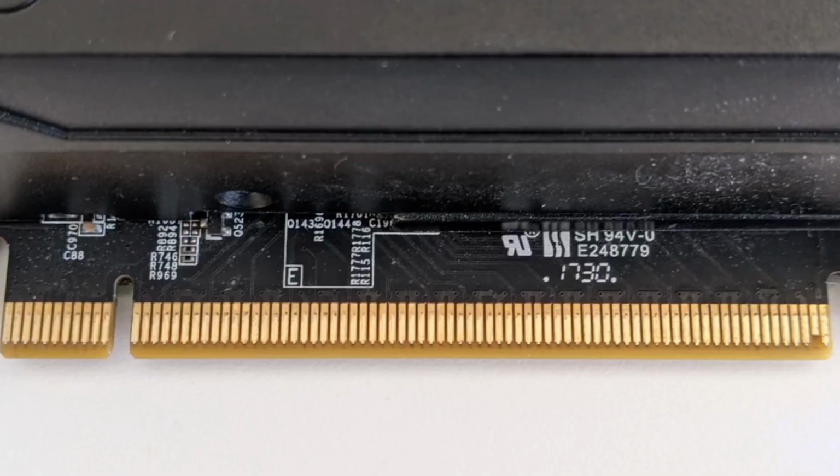There is often a brute force approach to solving this problem, provided the reference clock pins 1 and 2 on the backside of the board are still functional, and it usually involves technicians rewiring PCIe traces or soldering wires onto a donor mining board in order to reroute lanes. Let's first explore why these trace rerouting actions actually work and what these technicians are actually doing when rerouting the lanes. Here is a close-up picture of a GTX 1070 board I have on hand.